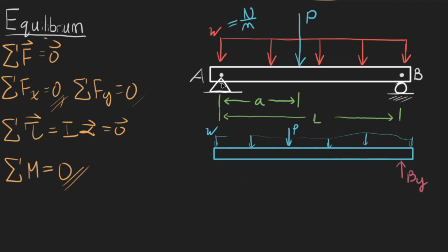And we also have a pin right here. So if you think about a pin, it's going to stop it from sliding past in any direction, but it won't stop it from rotating. And so what we say is that there's some force, but we don't know the direction, right? So basically we have 2 unknowns, like a force and an angle right here. So we don't know theta, and we also don't know the magnitude.